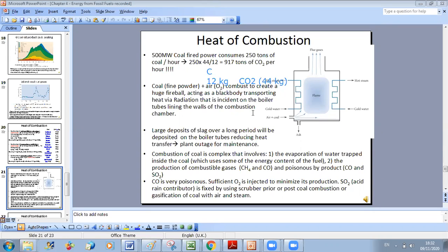Now, if you remember, in chapter 2 we saw that for fire, the main mode of heat transfer is radiation. Of course, if we put something directly on the fire, we can have conduction. And if we have moving air close to the fire, we can have heat transfer by convection, but the dominant mode of heating by fire is radiation, because we have exchange of heat through differences of temperature between surfaces.